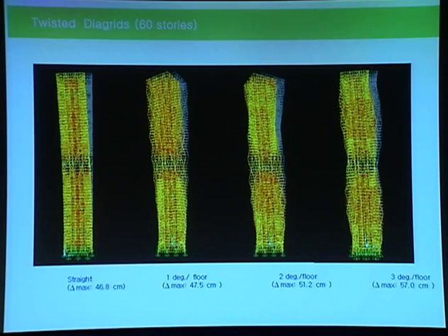If these structures are all solid, just considering an all-solid object-like structure, the moment of inertia of this solid object is all the same. So if you push it with the same identical concentrated load at the top, the lateral deformation should be all the same. But a building structure is not solid. It's composed of many different frame members.